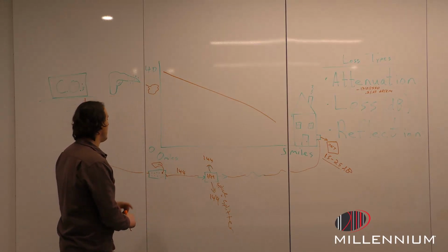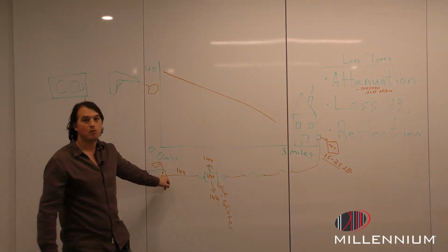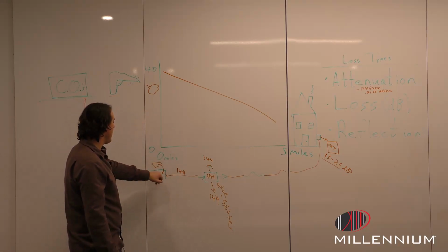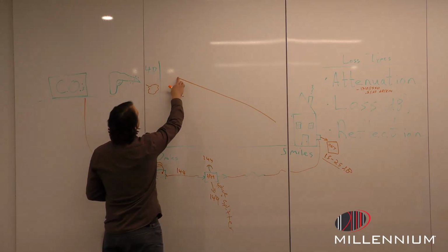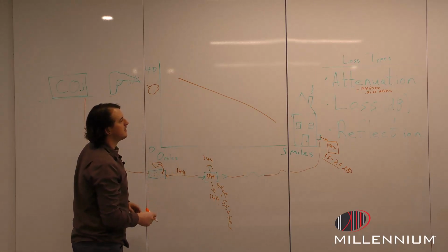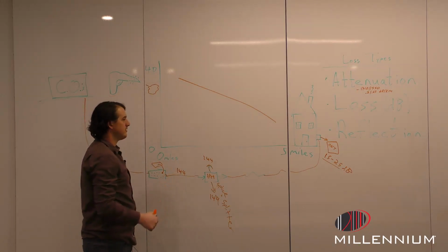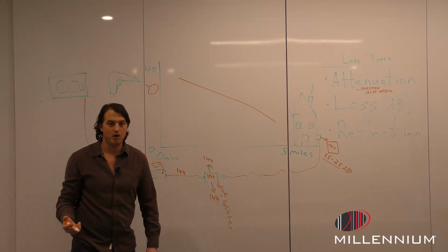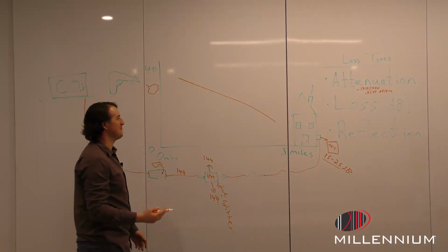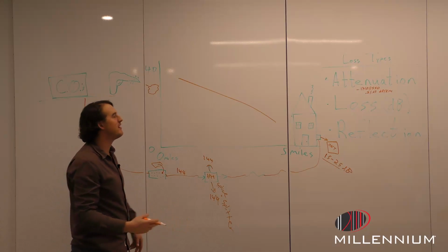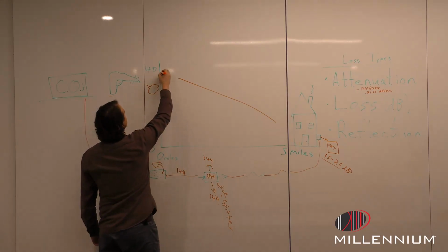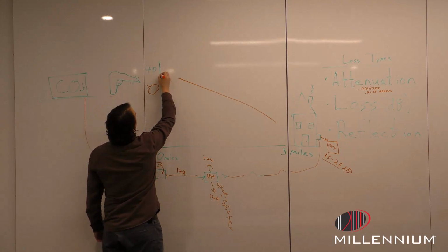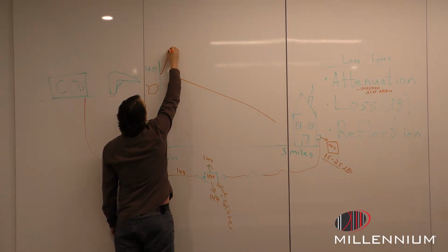What does it mean? All right, so starting out right here with our OTDR. As we plug in our OTDR, the very first event that happens is reflection. And reflection is probably my favorite one. If I had a loss type, yes, that's what I think about, is what is my favorite type of loss event. So reflection. What happens with reflection is the power bounces up.